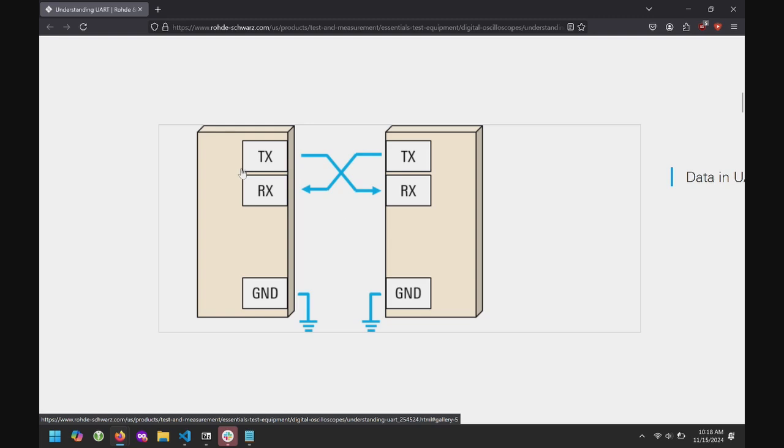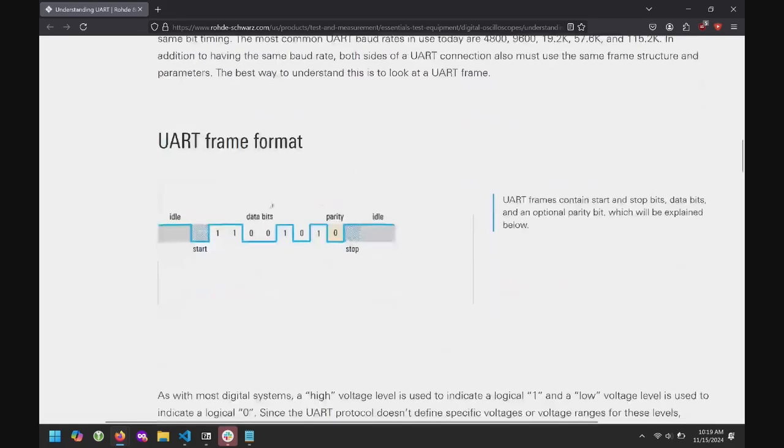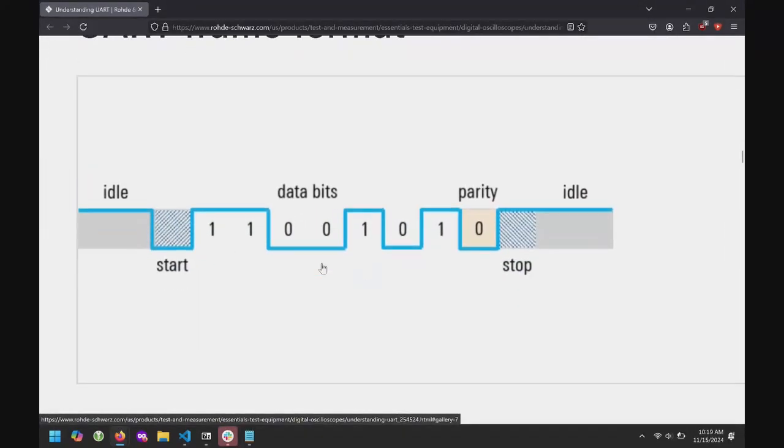The idea with UART is that for chip-to-chip communication, you will have a transmit pin and a receive pin. Each is just a single bit line, but it will oscillate, and depending on its oscillations, you send one bit at a time of the data you're sending. The transmit pin is plugged into the receive pin and vice versa, in a twisting pattern. If you only wanted to send data out, you could have just one wire, but if you also wanted data sent back, it would be two wires. So this is the general idea of UART.